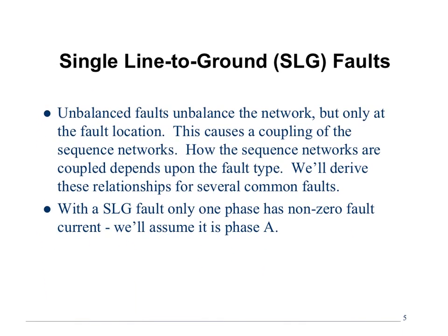All right, are you ready to look at unbalanced fault, single line to ground fault? Any questions? Because all we've done is what we did with homework, right? We took our single line and we figured out how to make a positive sequence diagram, a negative sequence diagram, and a zero sequence diagram. What was the next step? Build Y-bus for each of those diagrams, right? Once we have Y-bus for each of those diagrams, we can start to calculate fault currents as long as we know what the Thevenin equivalent voltages are at each of those buses.